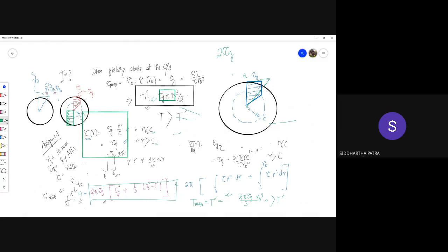This stress that is to be recovered is actually higher than the actual stress that happened in loading in some regions, and in some regions it is smaller. So in the end, this green must be subtracted. Once this green is subtracted, you get a stress state like this. All are shear, some are going negative in theta and some are going positive in theta.